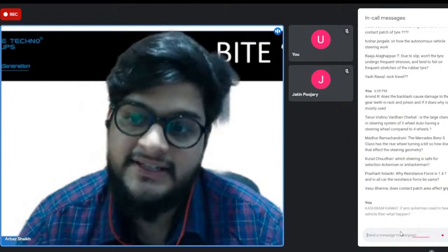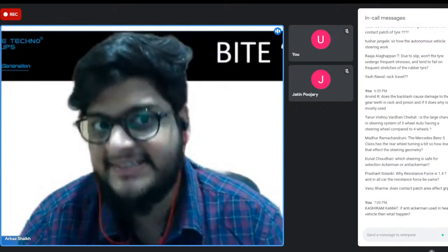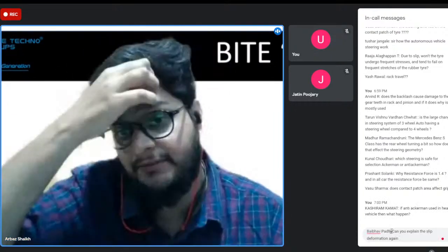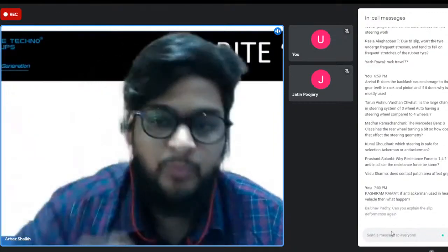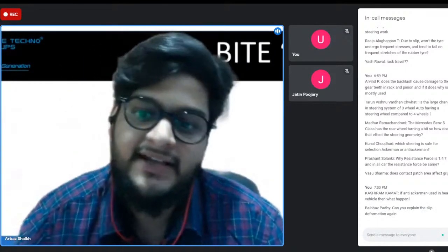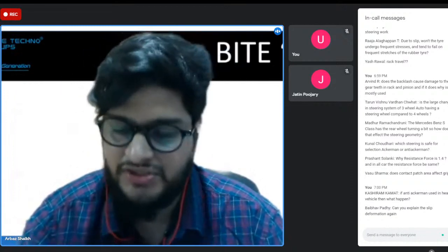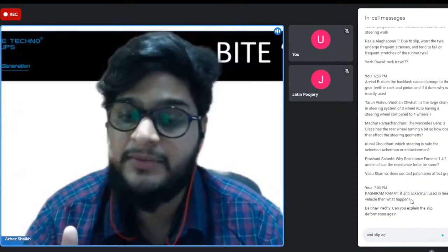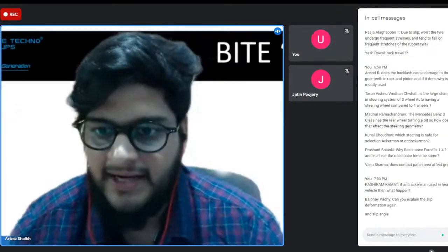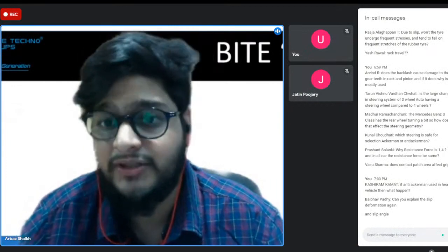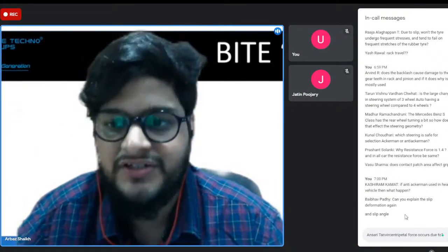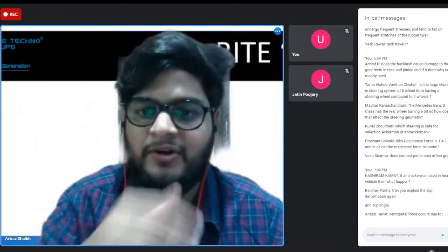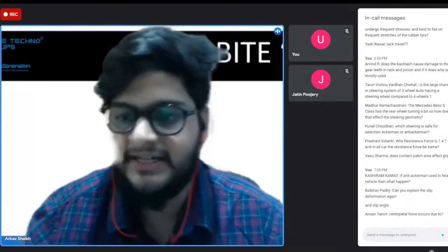Gauss is asking, what if the steering axis lies on the contact patch of the tire? That is the zero scrub radius region. First of all, it is impossible to use. See, the thing is, we can never be perfectly pinpoint when we do this kind of thing. We can either have positive scrub radius or negative scrub radius. When you have positive scrub radius, it's inside the tire, right? And if it's negative scrub radius, it's outside the center of the tire. And if it's negative, the effects are not that good. So you need to keep it positive for better calculation. It's preferable to keep it positive and not at zero, because in practical life it will never be at zero. It might go on the negative side also.